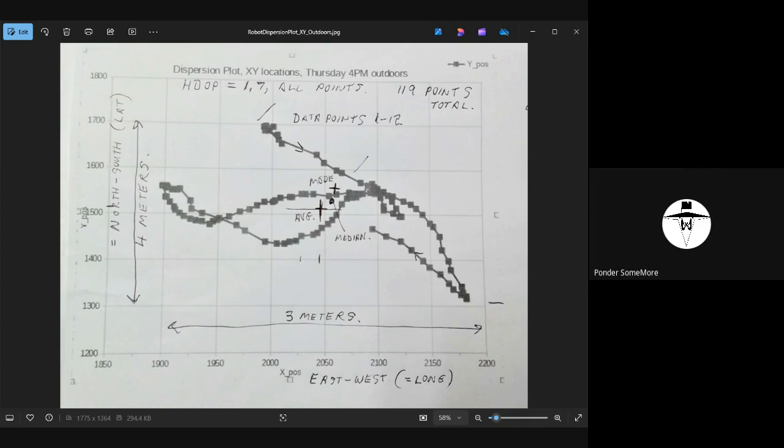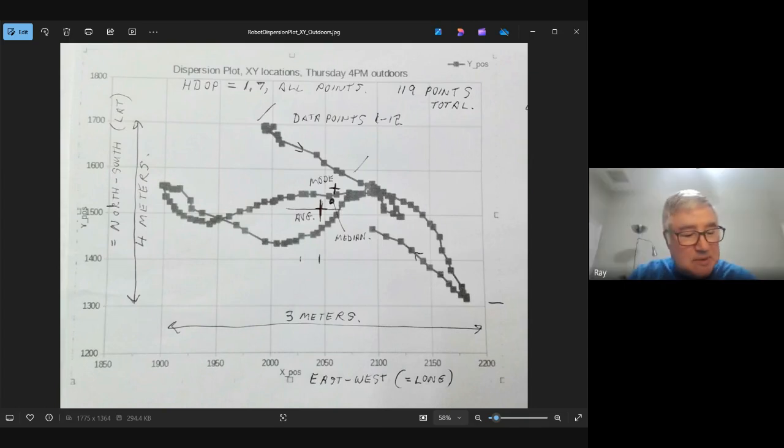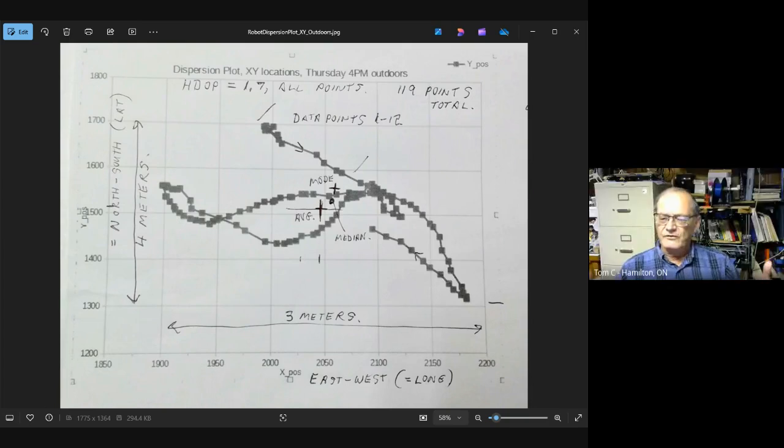Yep. Actually, I remember something they used to have in some of the cell phone parts, a low noise amplifier, LNA, and I think that's what's powered in the antennas that actually receive a DC voltage. Right. So you're saying it's probably an active antenna that I have. And in that case, substituting any plain Jane antenna off of the AliExpress shelf is not a good idea, since I have no idea what it will be.